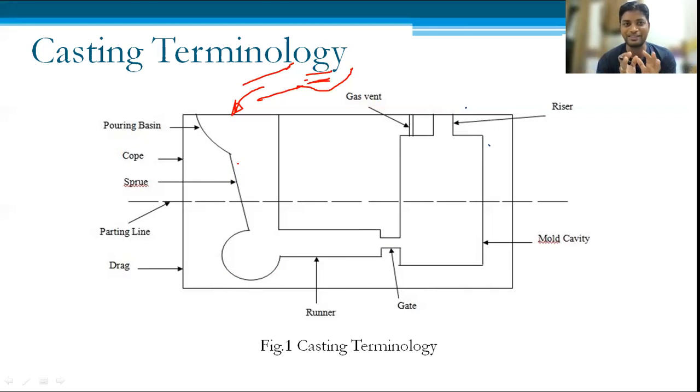Here it's casting, and it's not water. Whatever liquid material we are using is at a very high temperature, so we do not want any kind of spread, because it will damage the operator as well as the elements. We do not want impingement, so we keep the distance between the ladle and the pouring basin surface very small. We take it nearby so that there will be no spread.